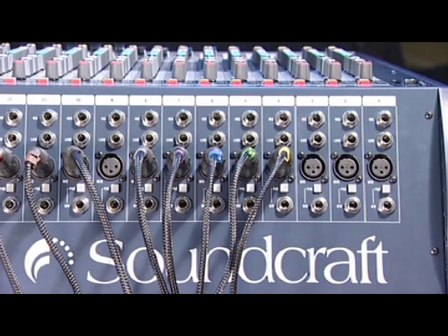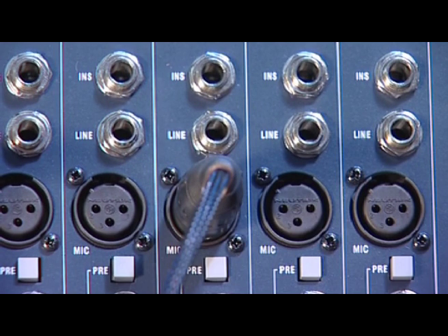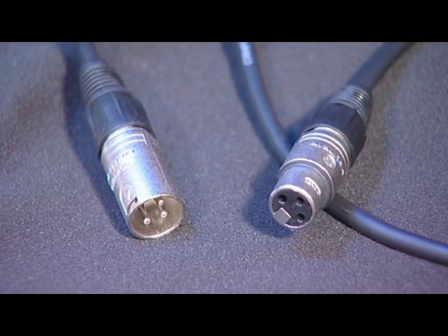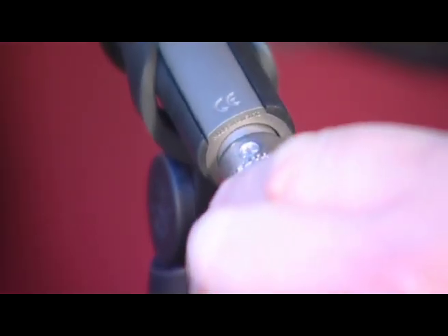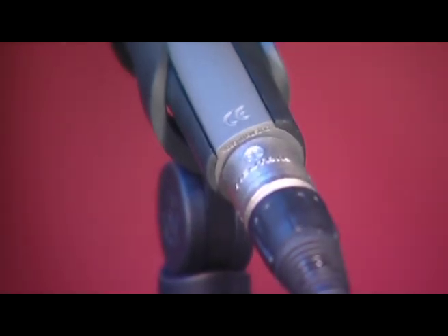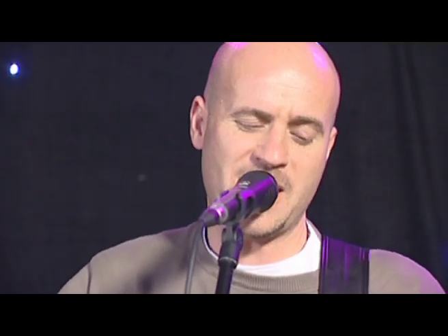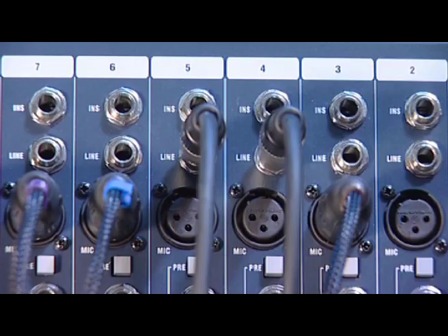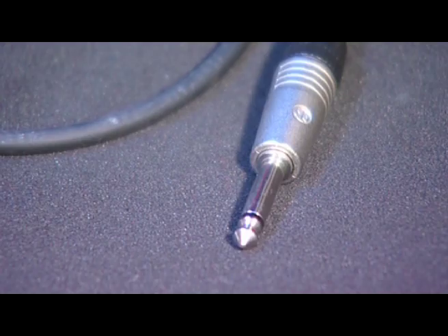Most mixers have a combination of mono and stereo inputs. You'll normally connect microphones to the mic-in socket, which will be an XLR connector. Mic inputs are almost always mono, and they're very good at dealing with the low-level signals that you get from microphones. Line inputs are for keyboards and sound generators, like samplers and MIDI modules. It's not a good idea to use line inputs with microphones because the signal levels are much lower than line inputs are designed for.